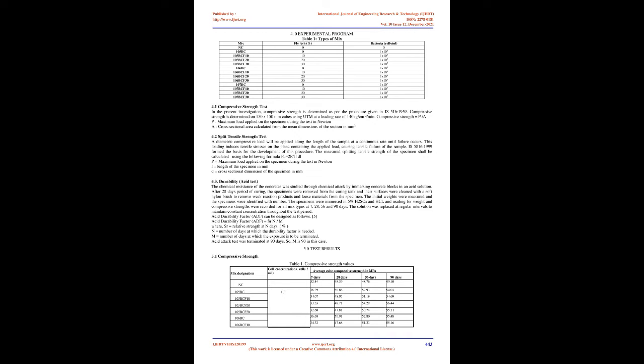Entry of harmful chemicals through these cracks may result in concrete deterioration through chemical attack and can also cause corrosion of steel reinforcement. This corrosion leads to increase in crack damage, resulting in loss of strength and stiffness of concrete structures. Even though there are many crack repairing techniques available through modern technology, such as grouting, gunniting, sealing with epoxies, and many more, the above-mentioned techniques are costly and also have high maintenance cost.